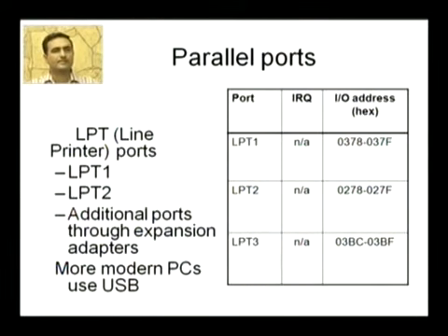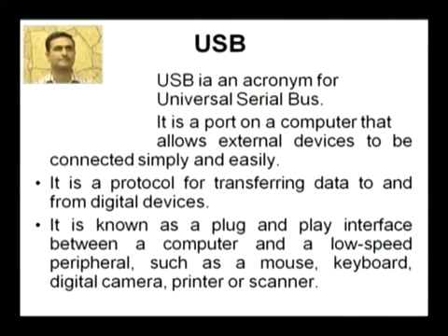And the various addresses for the parallel ports are, for LPT1, 0378 to 037F, for LPT2, 0278 to 027F, and for LPT3, 03BC to 03BF. And these addresses are shown as hexadecimal addresses.